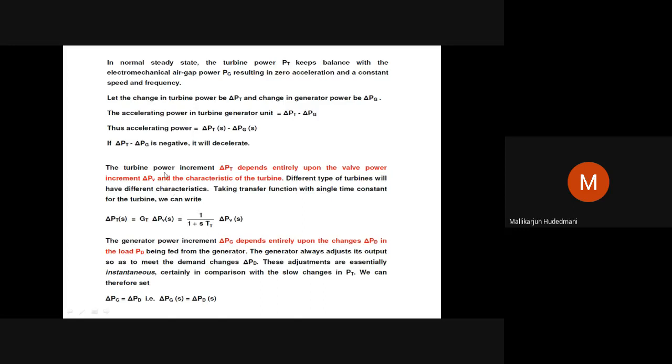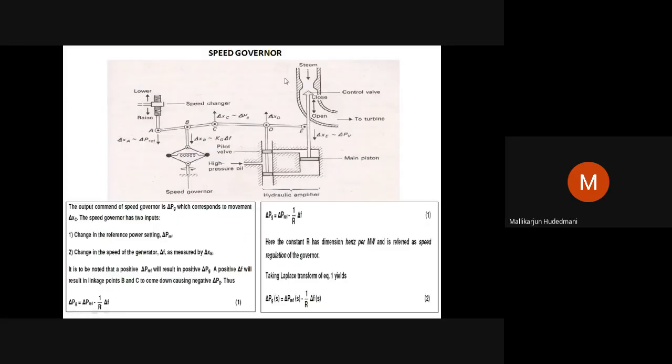For me, just to say how that mechanical input supplements your electrical requirement, I am trying to connect it. This is the subject of your next chapter only. But for me to connect how this turbine, with the valve opening and closing, relates to your generation, your set point and governor, I am trying to correlate it. Required change in input mechanical is nothing but demand change. That is done in two ways, one by set point change or by droop mode of control. That I am trying to connect to you.